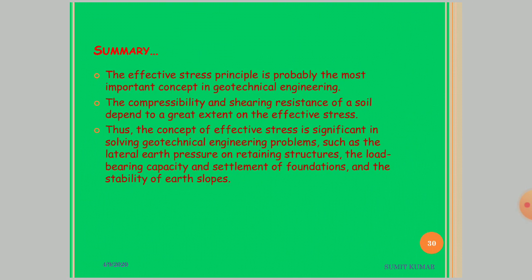The effective stress principle is probably the most important concept in geotechnical engineering. The compressibility and shearing resistance of a soil depend to a great extent on the effective stress. Thus, the concept of effective stress is significant in solving geotechnical engineering problems such as the lateral earth pressure on retaining structures, the load bearing capacity and settlement of foundations, and the stability of earth slopes.